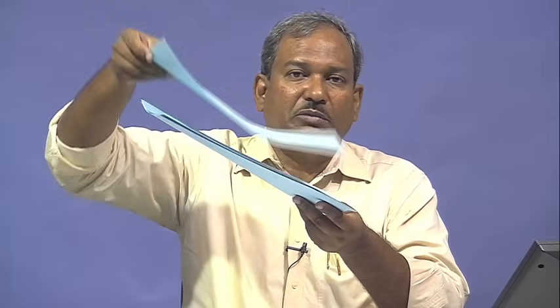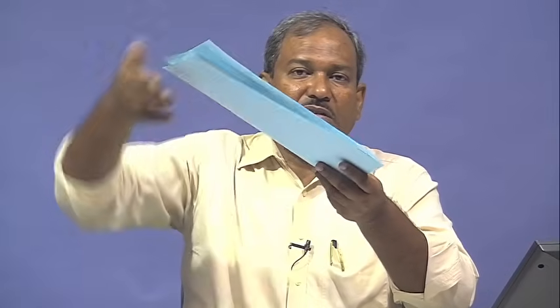So if these are the different layers that constitute my film, this is the top layer which is moving with the highest velocity, and the bottom layer which is in contact with the solid is static, it does not move. So there is a variation in the y direction in velocity. The velocity does not vary with x, the velocity does not vary with z, it only varies with y.